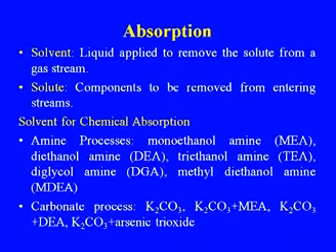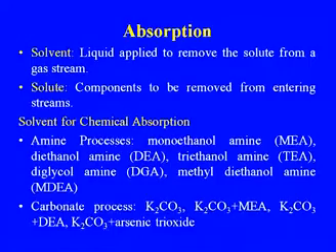There are two parts in this case: one is the solvent and the other is the solute, which is to be removed from the gas stream. So a liquid is applied to remove the solute from a gas stream, the components to be removed from the entering stream. As for the solvents, there has been continuous development in the case of solvents also. Now the amines: MEA, DEA, diethanolamine, or triethanolamine, diethylene glycolamine, or methyl diethanolamine. Some of these amine solvents are now being extensively used, even in refining.